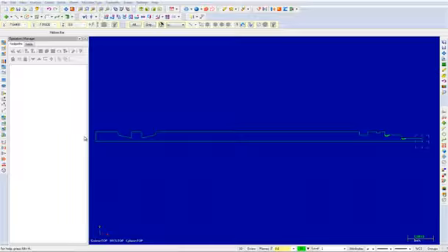The second tool is an OD finish right 35-degree tool. This tool will be used to finish the part. The third tool is an OD groove center narrow tool. This tool will be used to remove the material in the relief groove prior to cutting the threads. The fourth tool will be the OD thread right tool, which will be used to cut the threads.